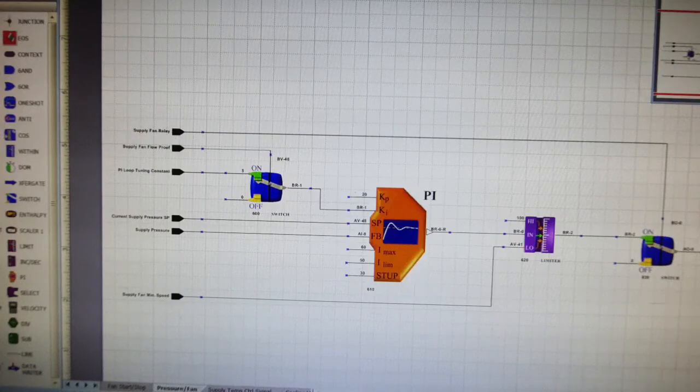You're not maintaining the speed for the VAVs as required. तो balancing के लिए और air के delivery के लिए for the respective CFM, ये VFD को हम लोग adjust करते हैं, like minimum speed, maximum speed. और VFDs could be from ABB, Danfoss, Mitsubishi. ये different types of VFDs हैं, variable frequency drives, जो control करते हैं फ़ैन की स्पीड को.